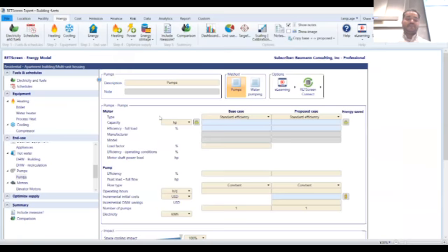Okay, so I have a recirculation pump that I can define out here. It is having a standard efficiency and it is having a HP rating of 0.0833. Or if you have a kilowatt rating, that is something that you can define out here directly. It is operating at a load factor of 75% and an efficiency of 80%. It is operating at constant load 24/7, and there is only one recirculation pump in the building. So this is something that I'm defining as a baseline case for my property.